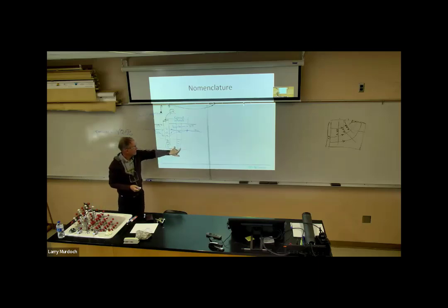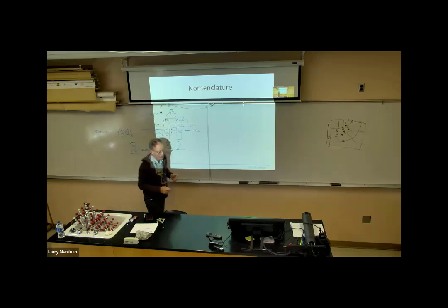And putting in a well like this, a monitoring well, is how we determine what the head is here and what the drawdown is. Measurements of the head and the drawdown will be what we use to analyze how the well is performing.